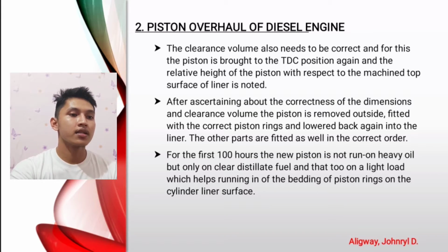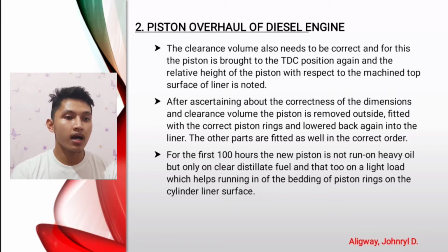And the next step is, after ascertaining the correctness of the dimensions and clearance volume, the piston is removed outside and fitted with the correct piston rings and lowered back again into the liner. The other parts are fitted as well in the correct order.